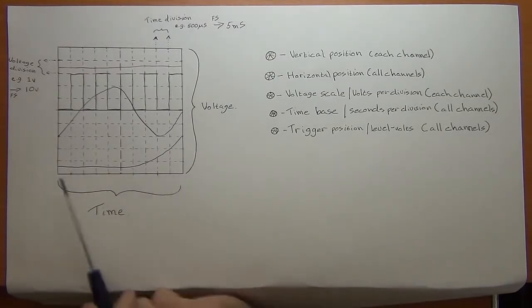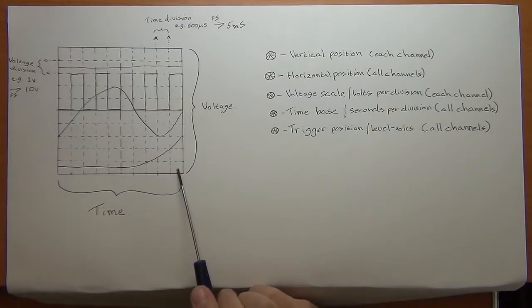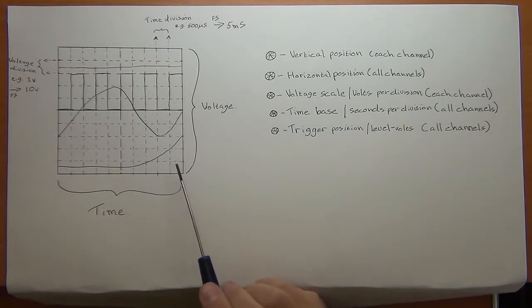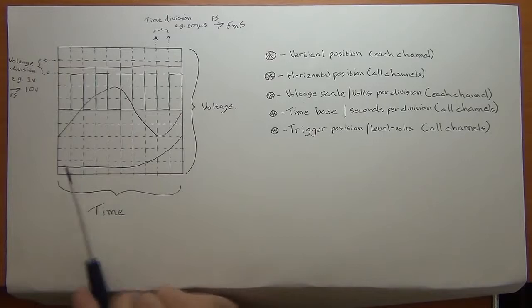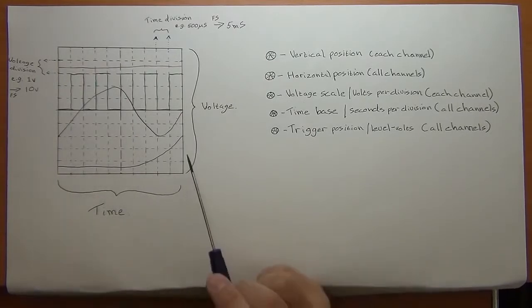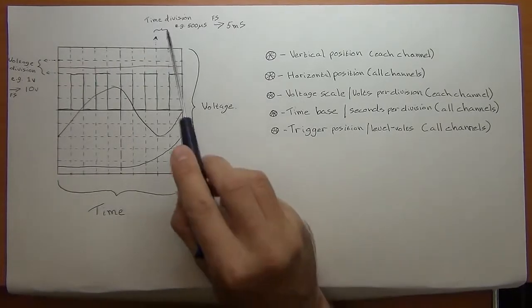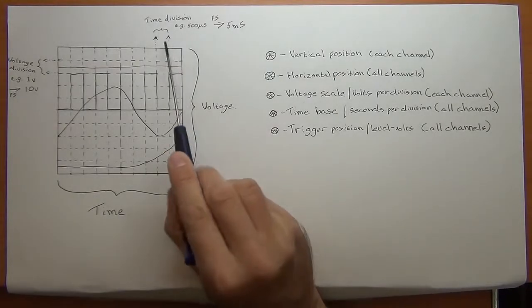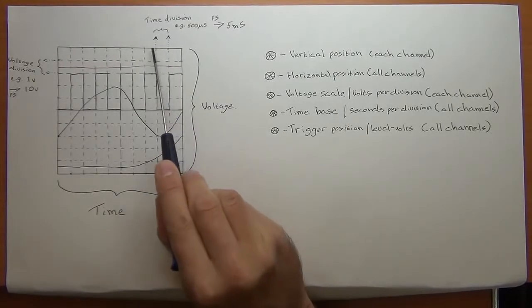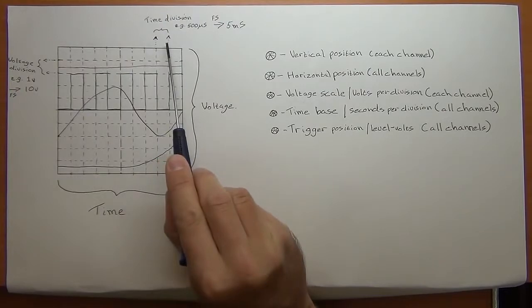Now that's known as your time base, and when you set your oscilloscope you can set what that time base should be, or it can be automatically selected for you, because you might not know the best time frame to view a signal. And as I've highlighted up here in the example I'm going to show you, each of those little squares is that division.